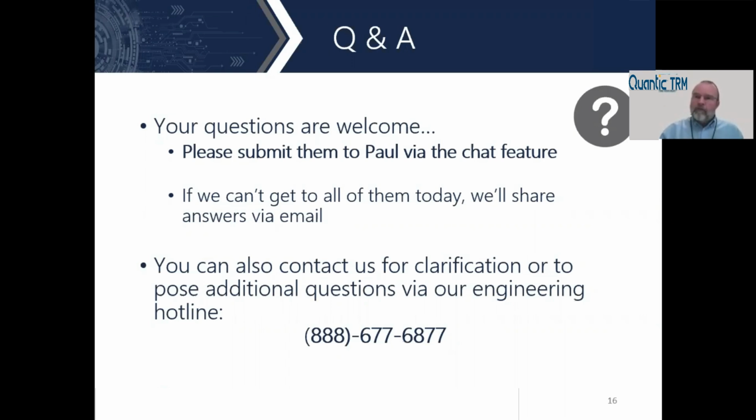That's a good question, and I didn't really mention it as we were going through the conversation. All of the printed couplers that I had in this presentation were strip line, and really the big trouble with having a microstrip coupler is the fact that microstrip is a non-TEM mode propagation as opposed to strip line, which is. What that means in layman's terms is that in a microstrip coupler, the velocity of energy going down that line is not linear across frequency. There's a dispersion that happens. As a result, because of that dispersion, you cannot build a physical structure that will have the same electrical length, whether we're talking about the even mode or the odd mode.